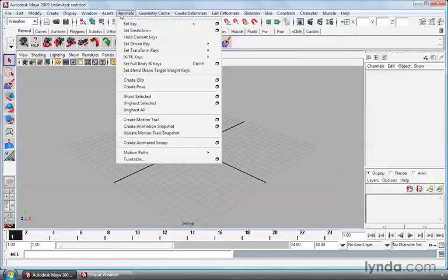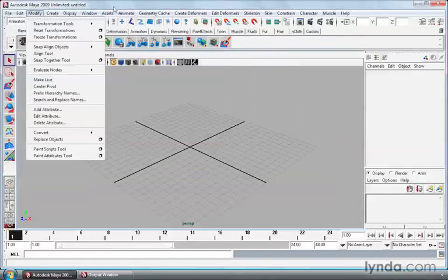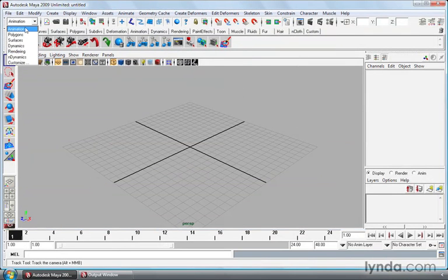Now, once we get to the ones here on the right, these are actually ones that can change. For example, right now we're working with animation. We have a pull-down menu here which actually changes part of that text-based menu. So, for example, if we are working with animation, we leave it here, and all the animation tools come up. If we are working with polygons, which means modeling, then we change that, and all of a sudden this menu changes. Notice how this menu changes when we go to surfaces, which is NURBS-based modeling, and rendering, and so on. The top line of Maya is not big enough to hold everything that Maya can do, so you have to kind of break it down into task-based stuff.